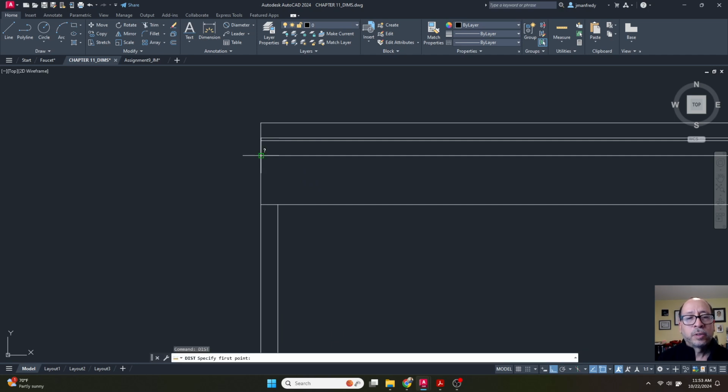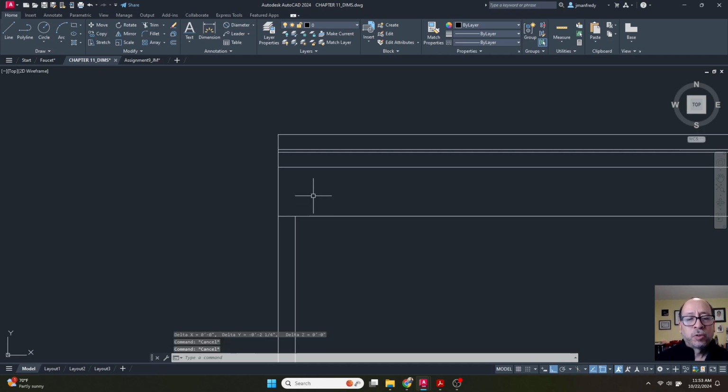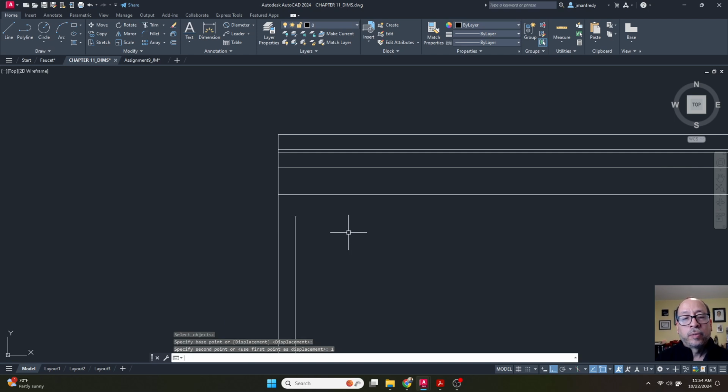And if I do a distance from here to here, this says 2 1/4. They'd like us to put a 3/4 inch radius. So part of it looks like it's going to be a full inch. So let's check some measurements here. Distance between this and this is 2 1/4, 2 3/4. Oh, I'm sorry, that is 2 3/4. This is 3 3/4. This line needs to move up an inch. This is what I have wrong. Extend command allows you to touch this, extend that to there.